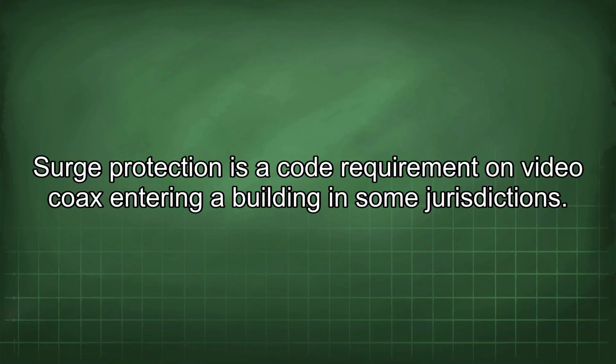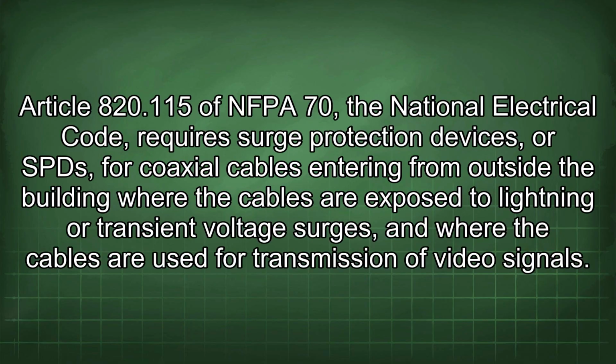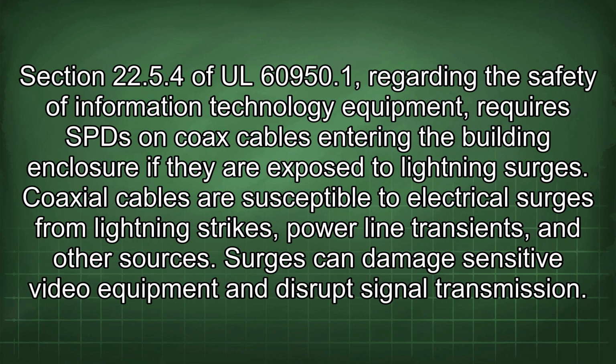Surge protection is a code requirement on video coax entering a building in some jurisdictions. Article 820.115 of NFPA 70, the National Electrical Code, requires surge protection devices, or SPDs, for coaxial cables entering from outside the building where the cables are exposed to lightning or transient voltage surges, and where the cables are used for transmission of video signals. Section 22.54 of UL